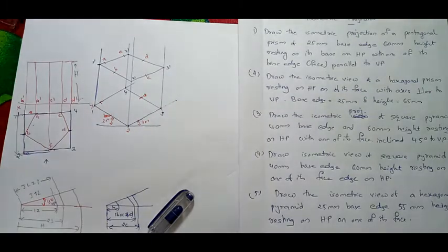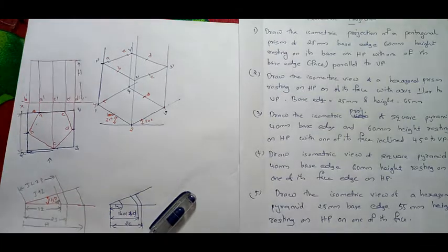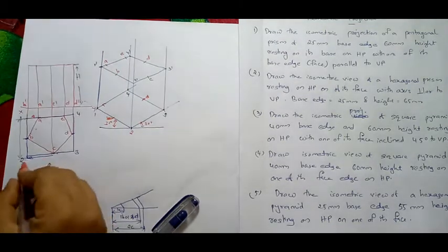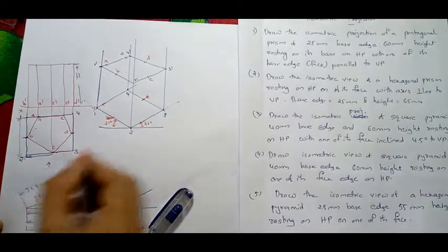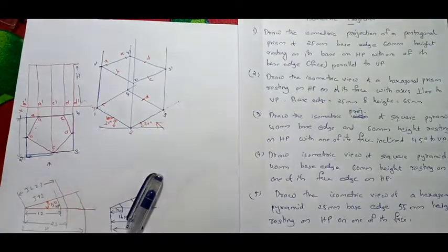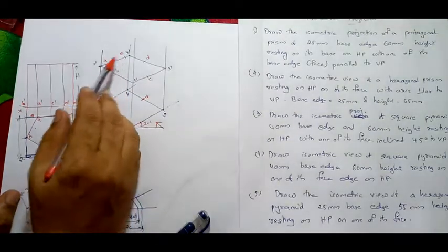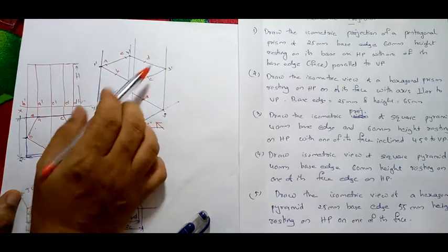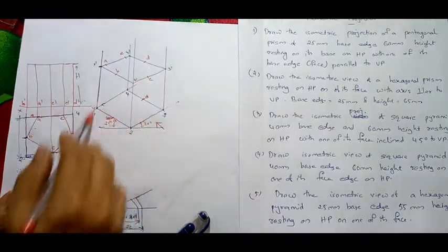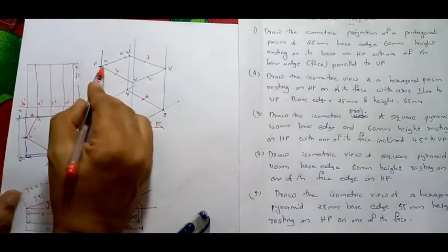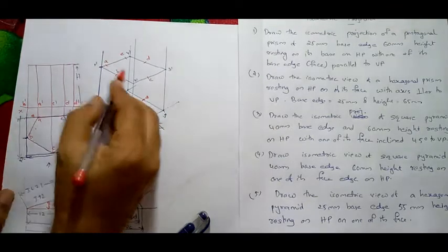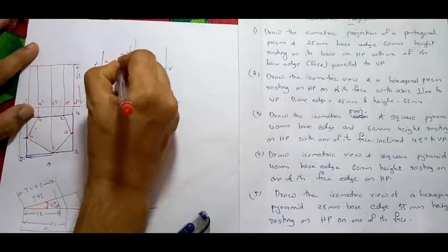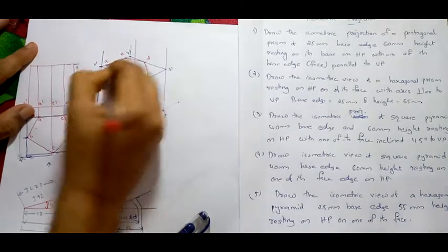Now visibility. Now I am going to construct the prism. Very simple. See, visibility you have to check. Here, basically after drawing this, you have to show where 2, 3. See, this will be your front view, right? So this edge you have to give an arrow here. This is your visible edge. So your visible edges will be top 1 dash, 2 dash, 3 dash, 4 dash. Then this edge is visible and this edge. These 3 edges are basically visible. So what comes inside these 3 faces you have to make visible. So first I will start from the top view. So we can join this A, B, D, C.